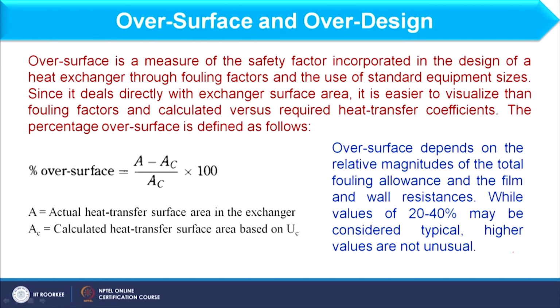What is this over surface and over design, which I am calling over design? I am calling over design the extra area. Okay. And why am I providing extra area? Because I am considering the dirt factor. Okay. So, we will find the overall heat transfer coefficient for the clean condition and for the dirt factor condition.